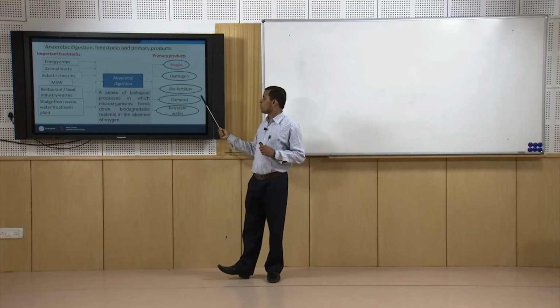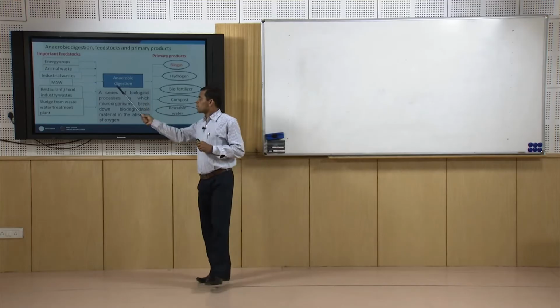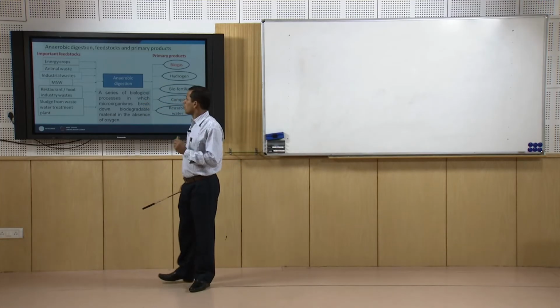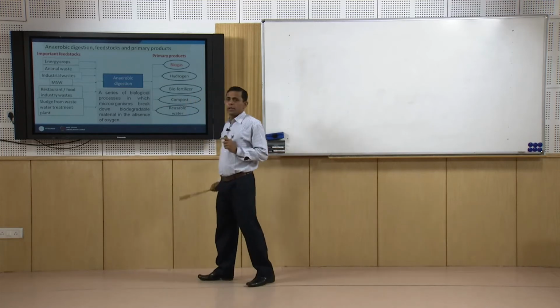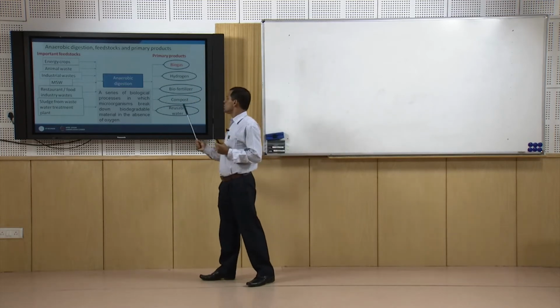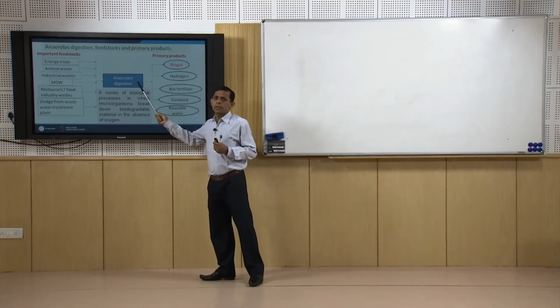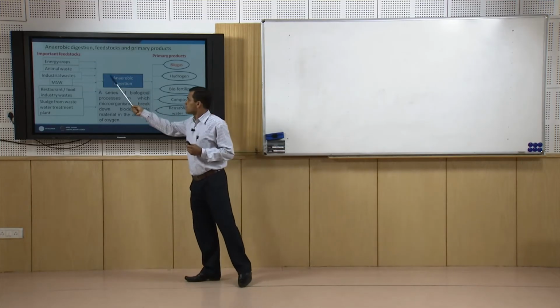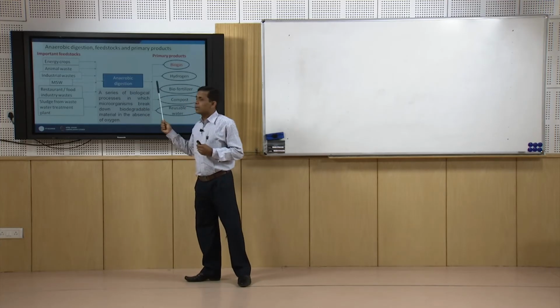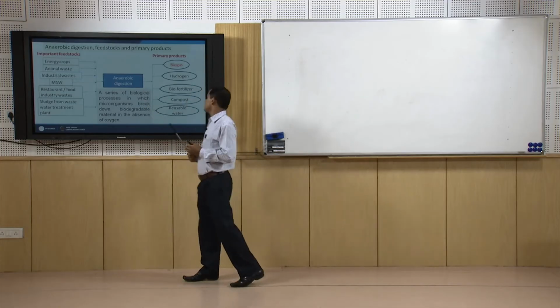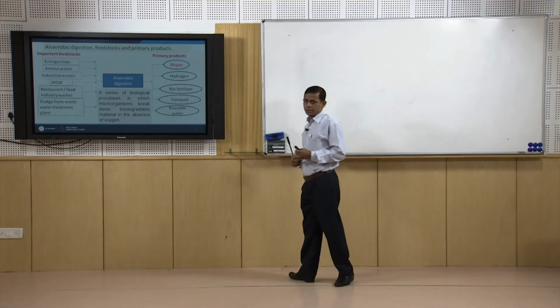So, compost can be formed, and in this process if we compare the thermochemical or thermal route with this biological route, the basic difference is that in this route we use a very large amount of water. So, the solid content in an anaerobic digestion unit, typically for a conventional anaerobic digester, is around 8% only.